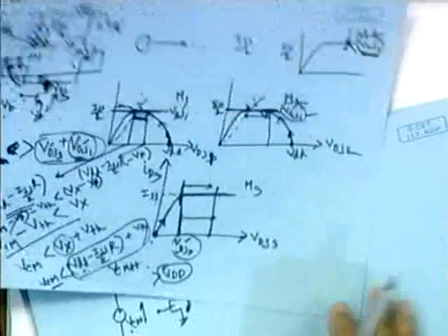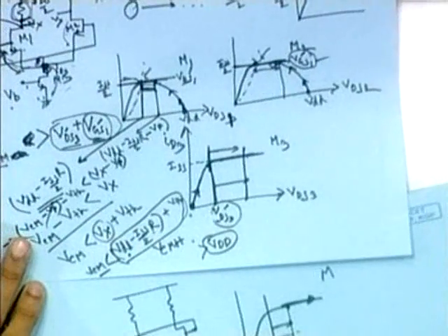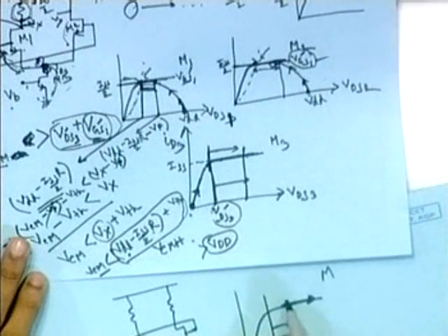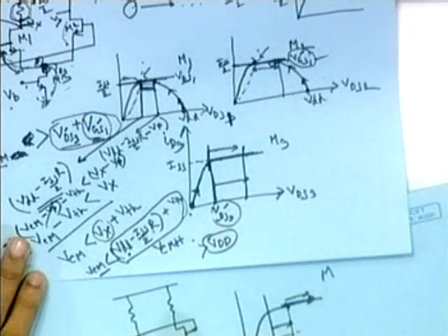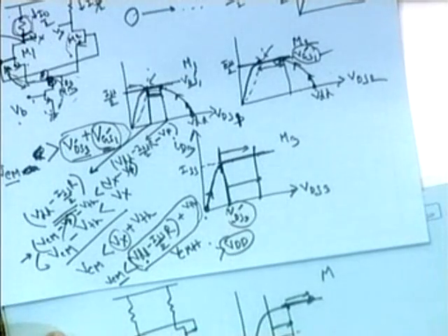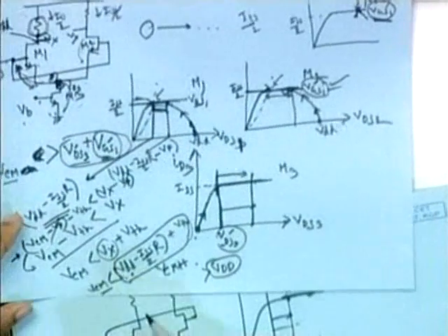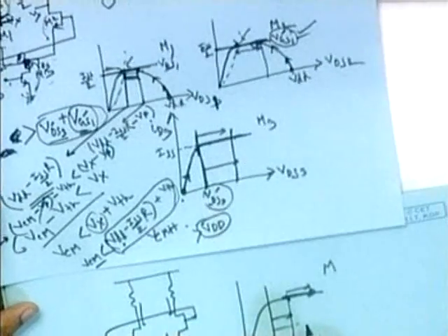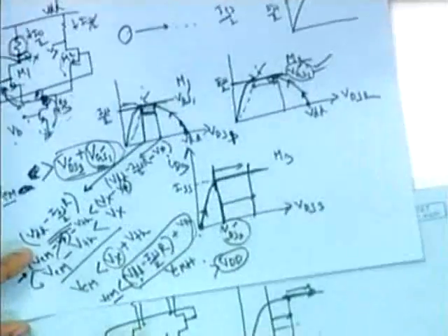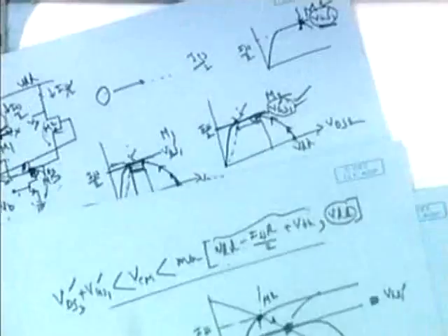If you increase your input CM voltage, this point moves along this line, so more and more voltage is dropped across this transistor. It maintains VGS1 constant at VGS1 prime, which maintains the current at ISS by 2. This is how it maintains the ISS by 2 current within this range.